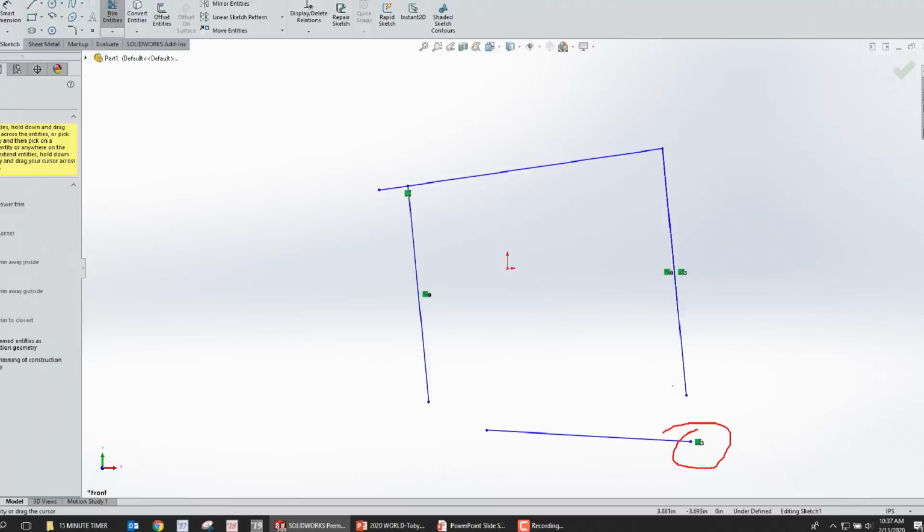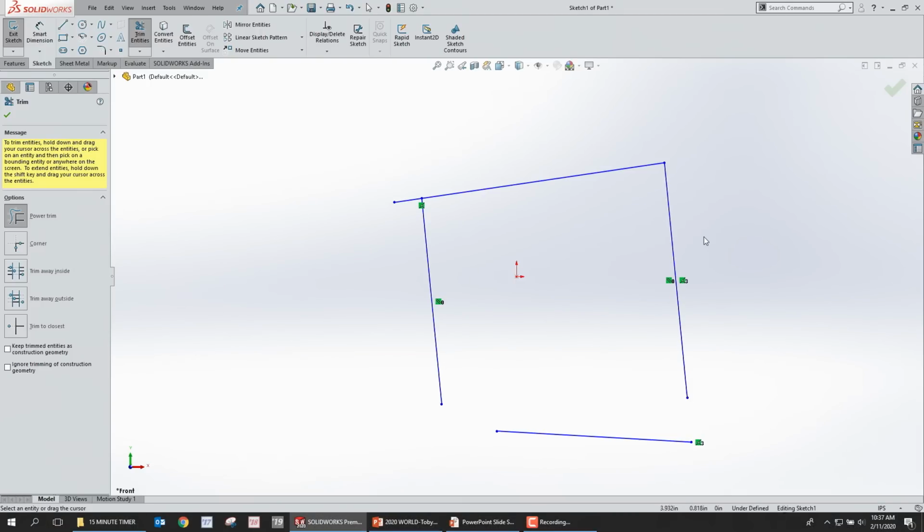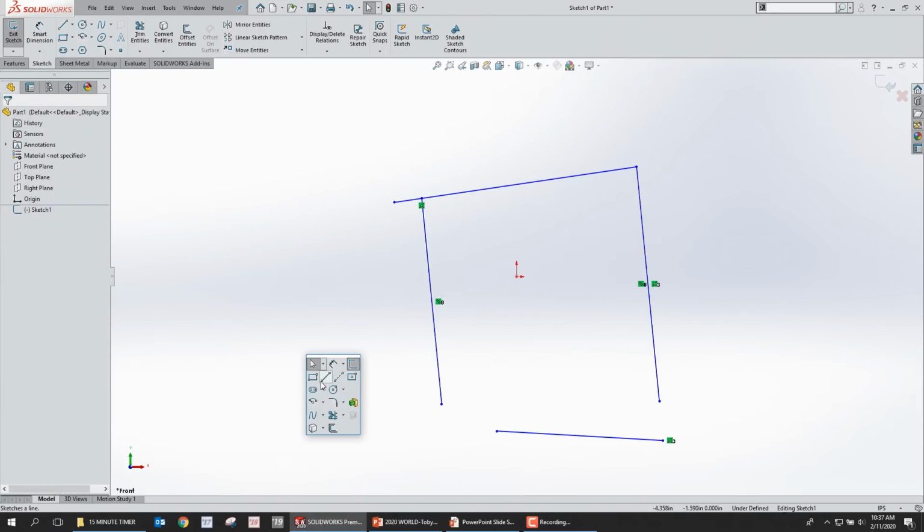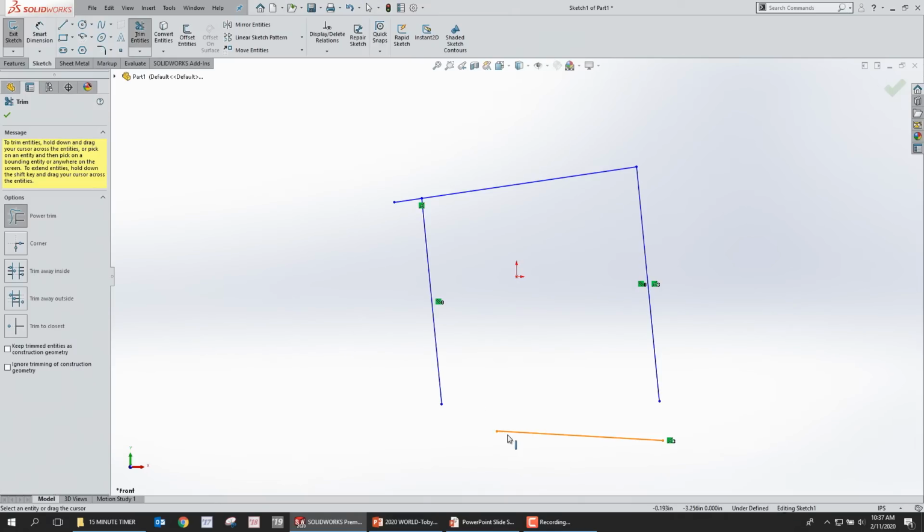Computer demagnify. So that's going to create a coincident relationship between this line and this line so that they're actually going to move together once you do that trim extend function. So you can actually use trim as an extend and a trim. You don't have to go into a different trim command. You can just do it right here. So click on that guy, extend it down to that guy, trim this guy off here, take this guy over to here.